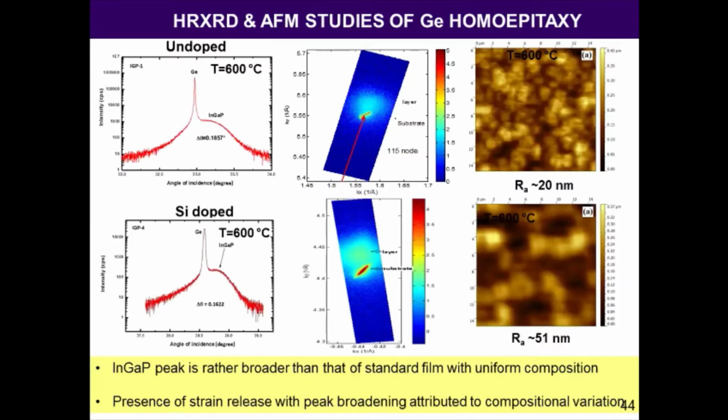So here you can see the mismatch for the epitaxial layer of indium gallium phosphide to grow, because the composition is not given. Indium gallium phosphide exhibits an indirect band gap for most of the compositions. If you take indium phosphide and gallium phosphide as the binary system, it is a ternary system, indium x gallium 1 minus x P. So in that way, we have to do it.